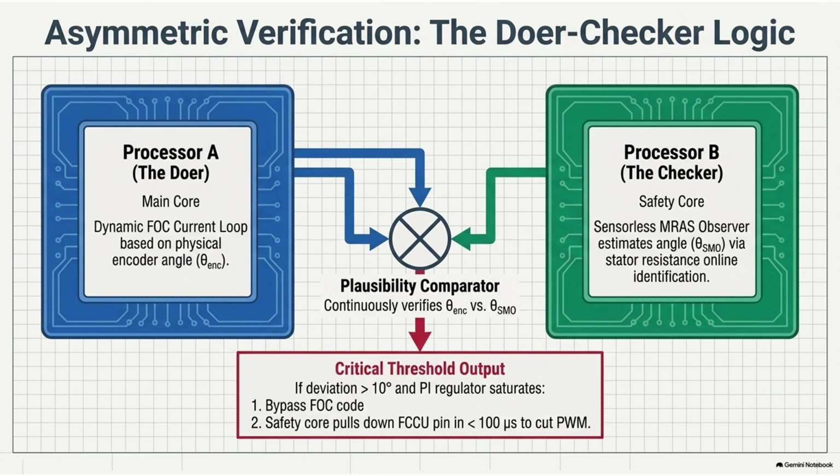Because short-circuiting the stator coils intentionally forces the generated electrical energy to loop harmlessly inside the motor's own windings rather than spiking back into the delicate electronics. Oh, I see. Yeah, the magnetic field created by the short-circuited current actually opposes the rotation of the rotor, acting as a massive electromagnetic brake.